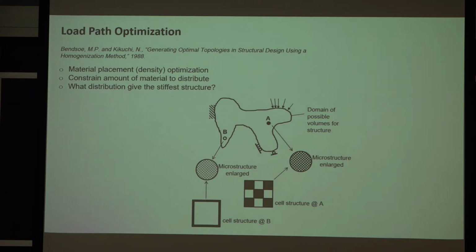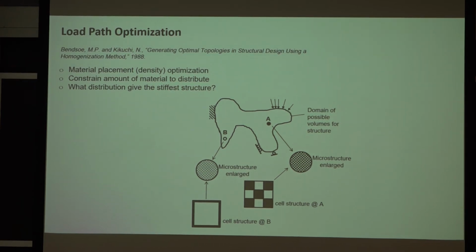And then they used finite element analysis to discretize this random looking structure into a bunch of elements, okay? And then they say the density of each of these elements can go between being fully dense, which is a 1, or having no density, which is a 0.